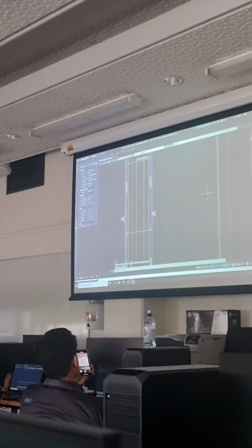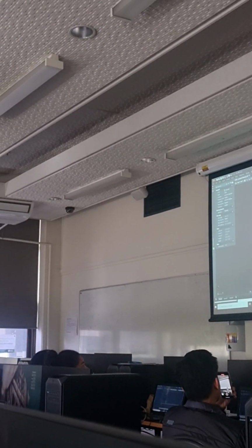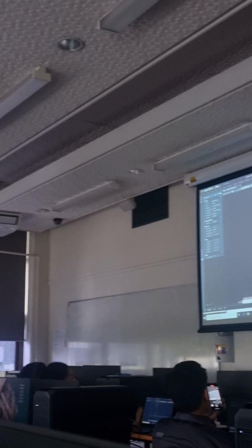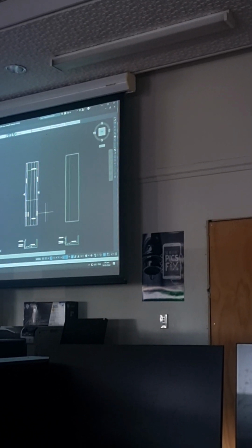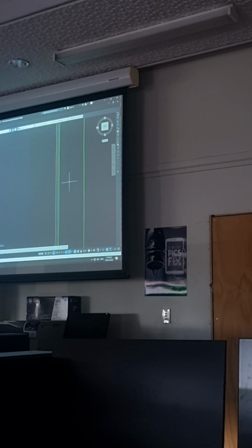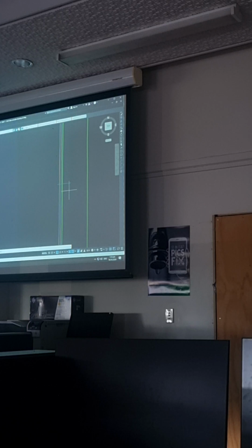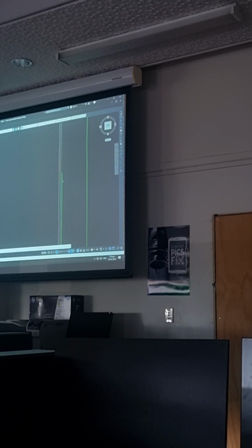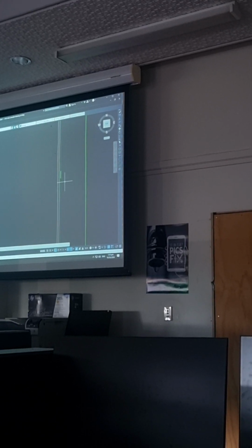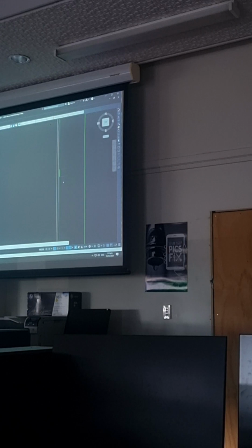Now, of course, you're all saying to me, that's way too big to eliminate a bar, and yes it is. So I just put a couple of lines across. No particular length, but if you can make it similar to my drawing, which is probably a wee bit too big, probably about that. And I'll just go trim, my favourite command, trim, and get rid of the construction lines.